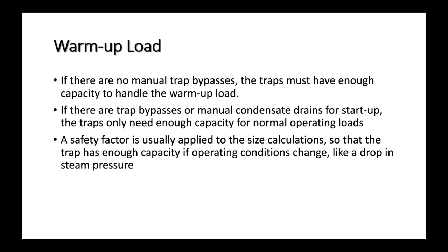So in other words, the thermostatic traps all require subcooling to discharge, whether it's a pressure balance trap, a liquid expansion trap, a radiator trap, or a bimetal trap. They all rely on that. Now, once we get into the mechanical traps, the float thermostatic doesn't care whether it's subcooled. It'll discharge the condensate because it is responsive to the density difference between condensate and steam, right? So anyway, I digress.